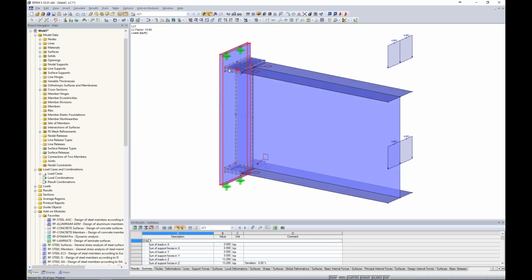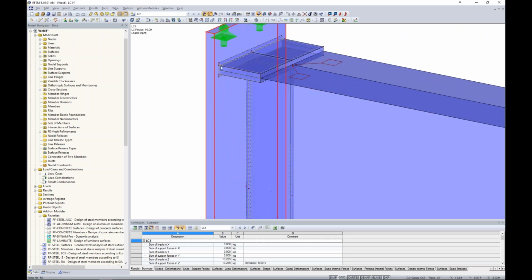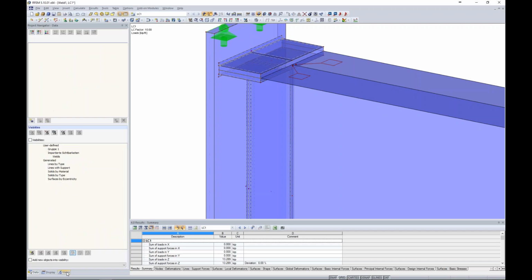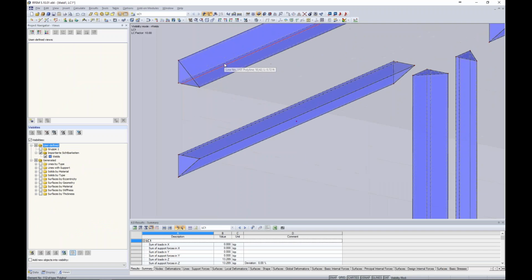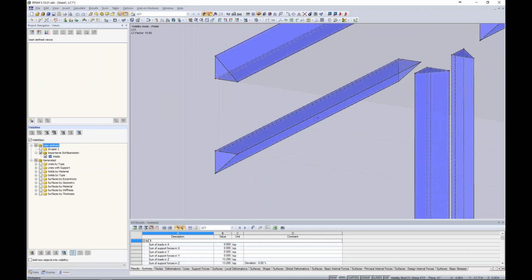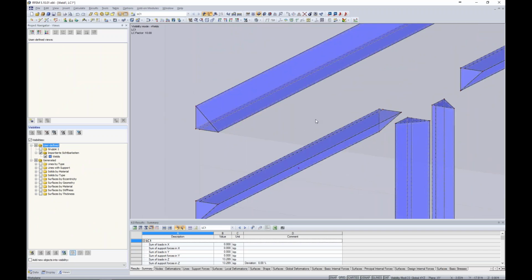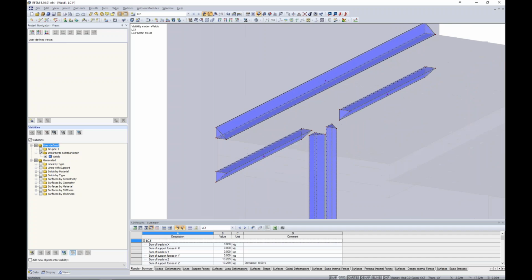So you'll notice we have many different lines and elements framing into the front side of the surface A, but we don't have it shown on the back side. So how about the welds? Well, I created a user-defined view here, and I can turn this on, of my weld solid. Zooming in here, you can actually see the triangular shape of this fillet weld, for example. Now, this weld is just another solid element.